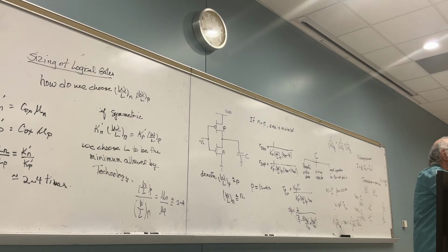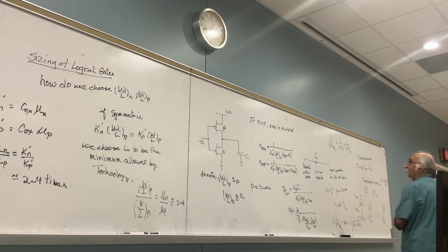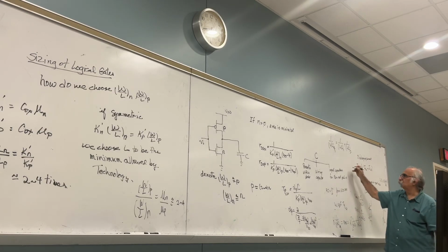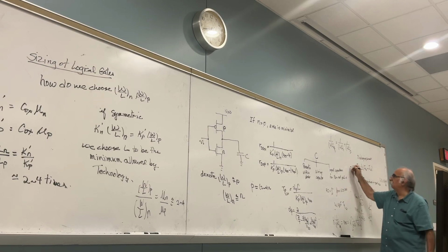Series transistors, if you put series transistors, the overall W over L is calculated equivalent to the way you calculate resistances in parallel. Did you get it or not? I ran out of time. Next time we'll continue. But answer me the following question.